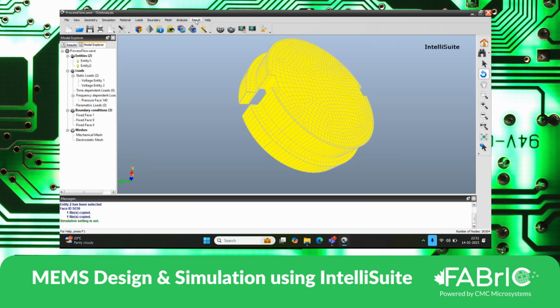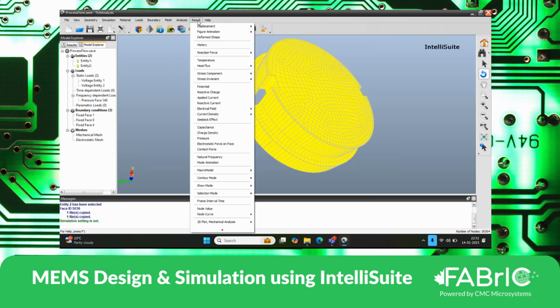Once the simulation is complete, we go to results and then we click on modal contribution. Modal contribution gives us the dominant mode, which is typically the primary mode, and we try to disable the other 2 modes.